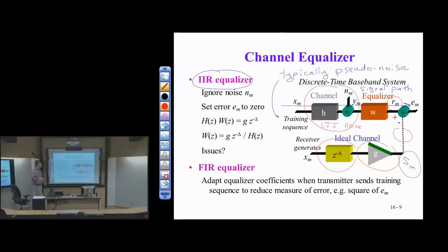In homework, what you're going to look at is let the delta, this delay, be no larger than the worst case delay through the equalizer, which is the equalizer length minus 1. So in homework, we're going to set the equalizer length and then search over all possible delays, get the best equalizer, increase the equalizer length by 1, search over all delays, get the best equalizer, and we're just going to eventually find an equalizer that will drive this error to the smallest value. So we also have to limit how long the equalizer can be. So we have to set an upper limit on that. I think I tell you 40 or something in the homework. Go ahead.